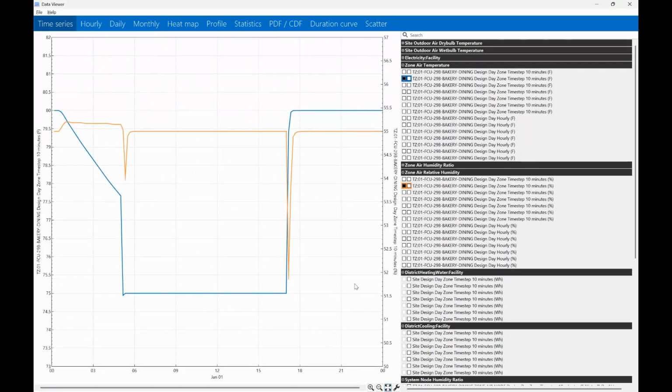All right. So this is with humidity control, and you can see it's actually controlling pretty good. Humidity is in orange, and it's pretty flat across here. These dips are when the system starts introducing more outside air, or when the building becomes occupied or unoccupied throughout the day.